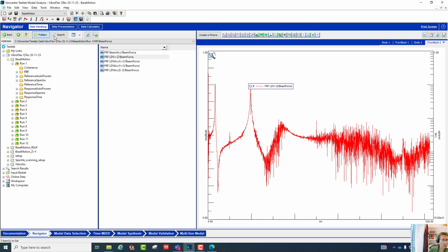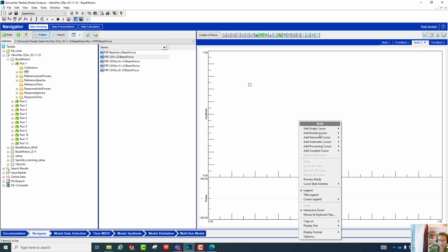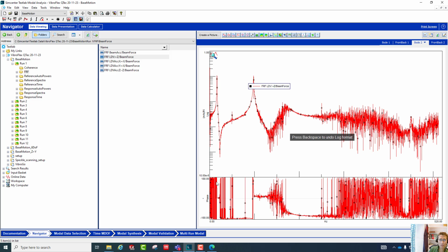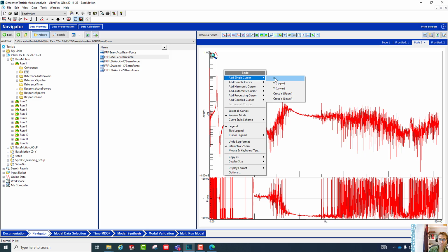So that's an introduction to the nature of the project, how we can investigate these functions within the Navigator, how we can preview them. There are lots of options to plot them. Probably I should show the Bode plot as a preview mode. And there you go. So now Bode plot preview mode, we can change the limits on this axis to log, and phase is displayed down here. So phase, remember, doesn't really have a meaningful value except as we pass through a resonance.